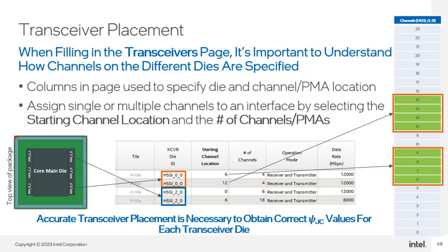Providing die-specific transceiver use information is critical in performing an accurate multi-die thermal analysis. As you edit values in the PTC, make sure to look at the warnings and errors window in the tool to see if there are any errors with any of the settings you have selected, such as overlapping transceiver interfaces, before going to the thermal analysis page for the final results.